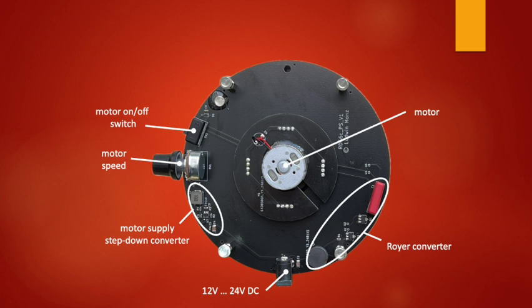However, there is one critical part of the Royer converter circuit that caused me major problems at the start of the development, namely the complex coil arrangement. This involves a so-called bifilar coil and a feedback coil, each of which have to be connected in the correct phase. However, all the problems with the arrangements were solved by designing the coils as printed circuit on the board. They are located on the back of the PCB, and in this way the circuit is really absolutely reliable and easy to replicate.